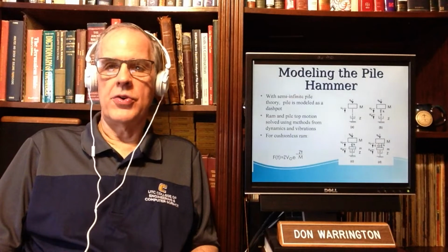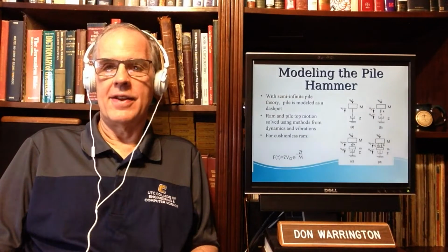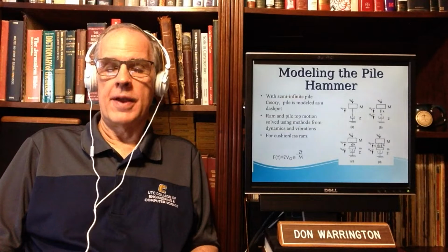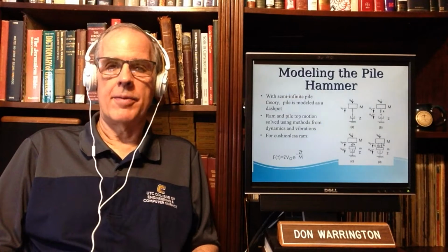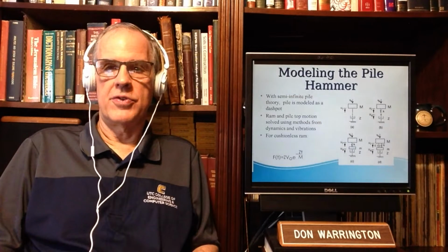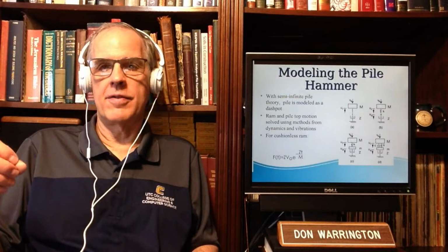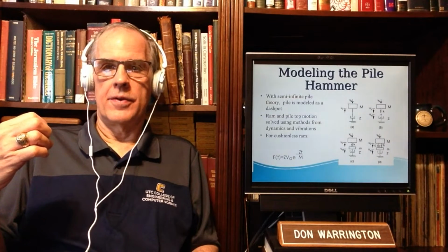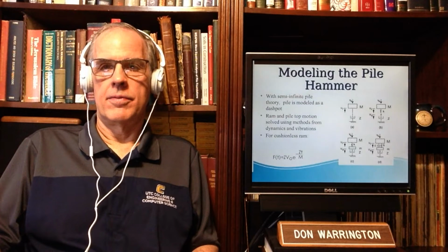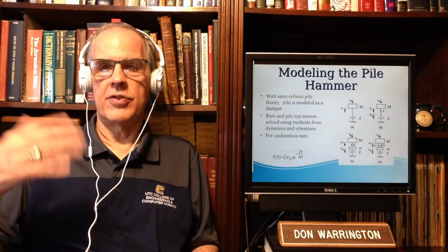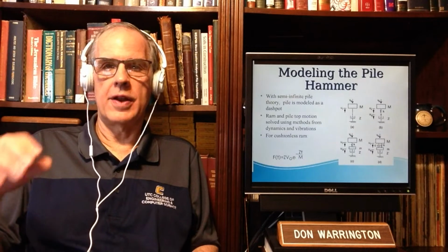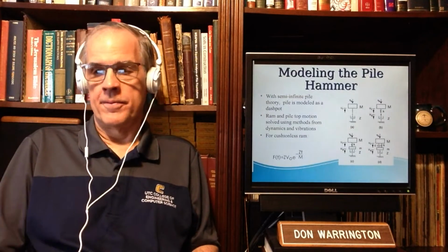One thing we can do, and it's been done in several studies, I did it for my master's thesis here at UTC, was model the pile and hammer semi-infinitely. In other words, we ignore the reflections. I can estimate the response of a pile to impact without reflections, and I can find out what kind of loads are on the pile, what kind of loads are on the hammer, and that kind of thing.